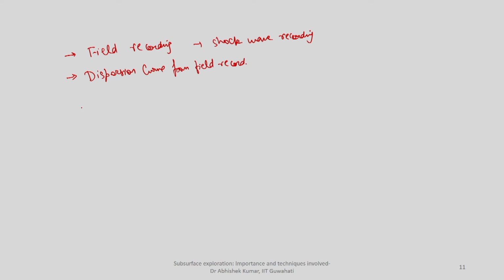Okay, one important and last parameter here is that the entire test consists of field recording, that is based on geophones you will put and try to record. So, shock wave recording, then dispersion curve from field record, and the last part is determination of shear wave velocity profile or Rayleigh wave velocity profile based on inversion.